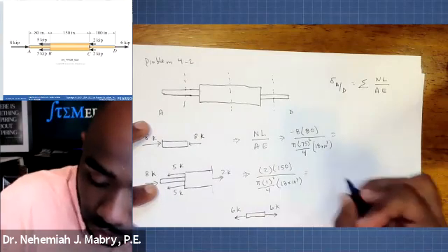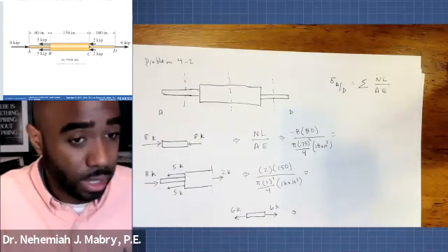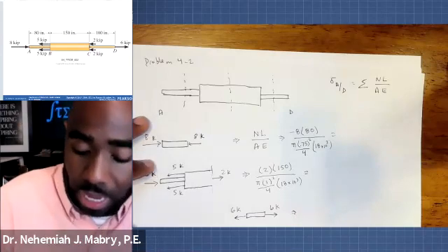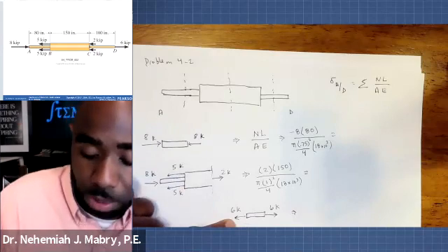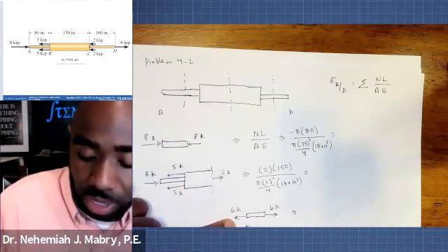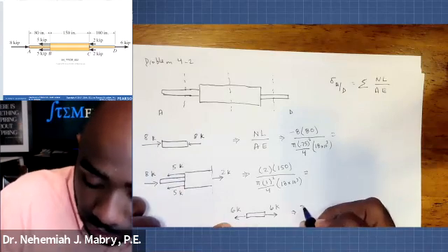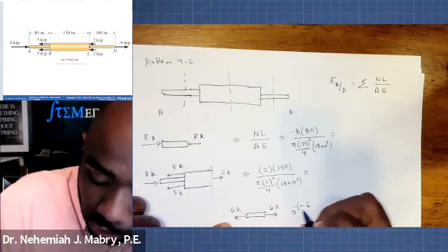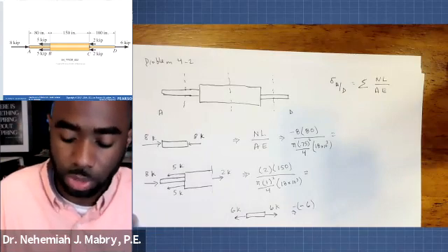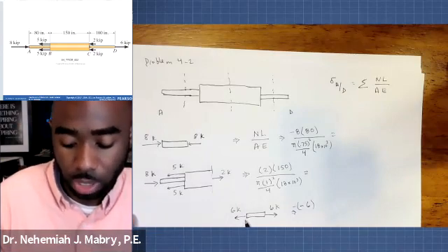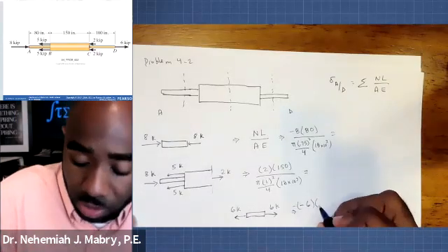Lastly, we're going to come back and do the math behind all these. Lastly, we're going to come over here, and the internal load in this case is 6. But because we're going the other direction, we're going to change our sign. Ordinarily, this would be a -6, but because now we're looking at it from the other side, we're going to change the sign to be consistent. The length of that section is 100.